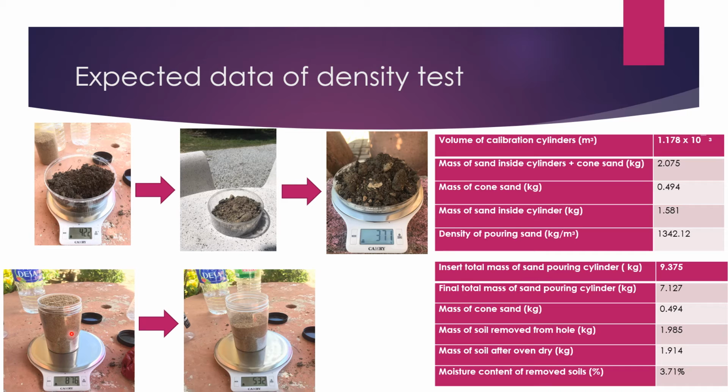And this is the Ottawa sand. This is the original weight of the Ottawa sand before I used it to fill the hole. And this is the current weight of the Ottawa sand after I used it for sand replacement testing.